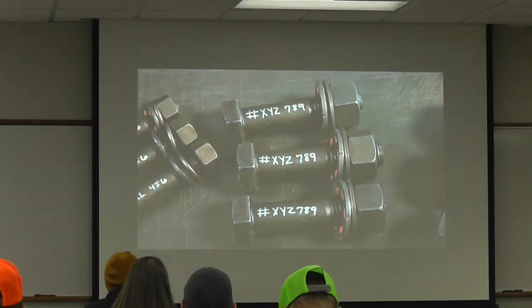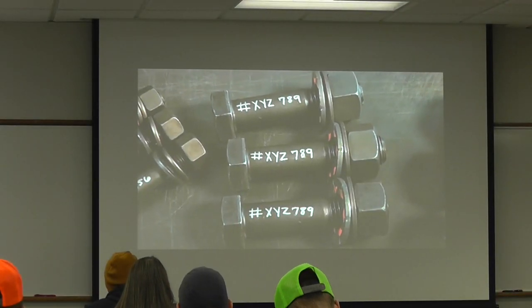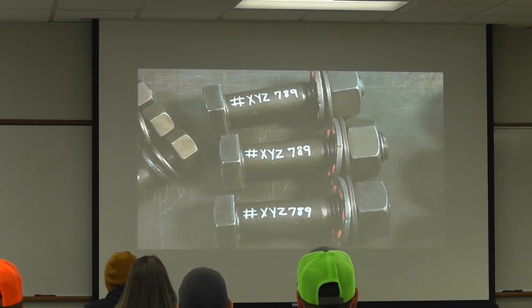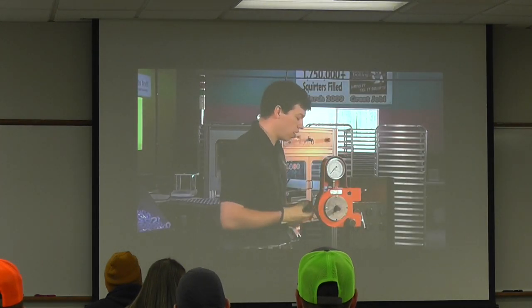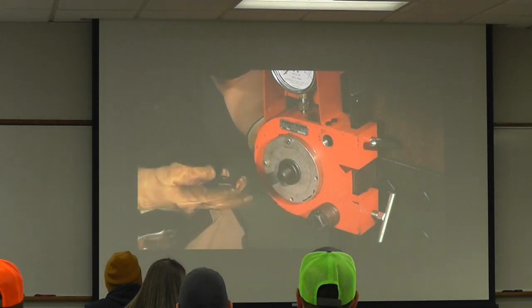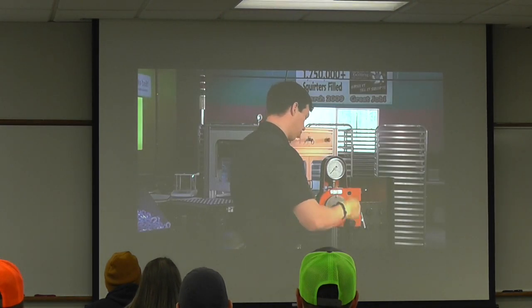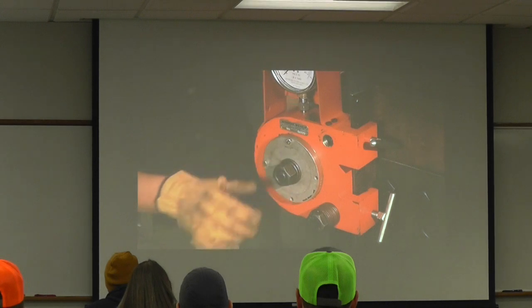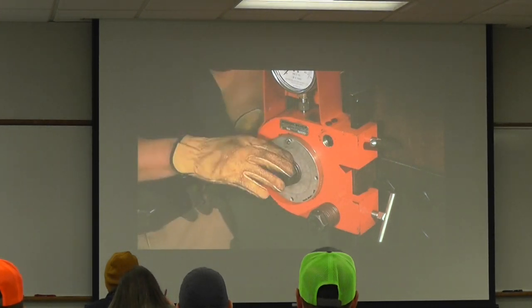For our test, we're going to use 1 fastener combination: a 7/8 by 3 A325 bolt, our squirter DTI, an F436 washer, and then our DH nut. And we're also going to be tightening this from the nut side.